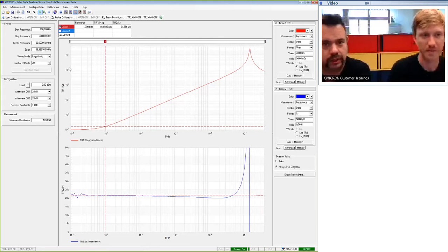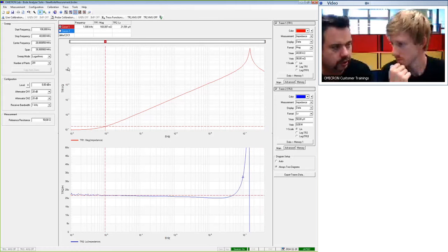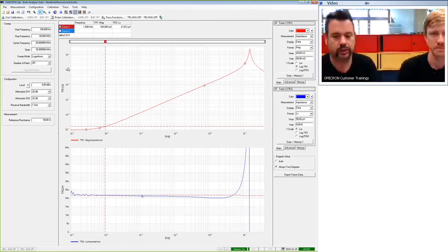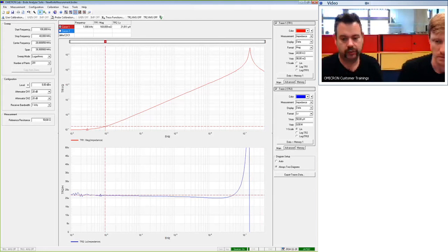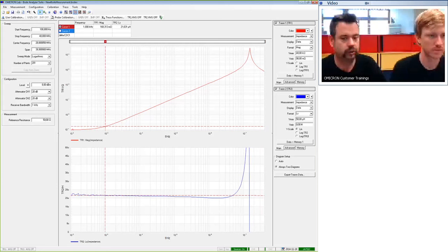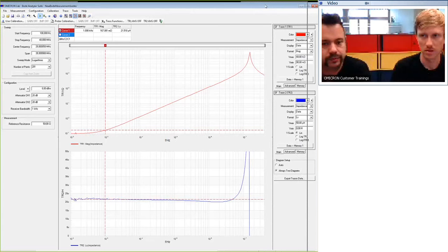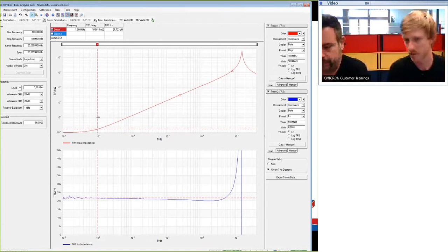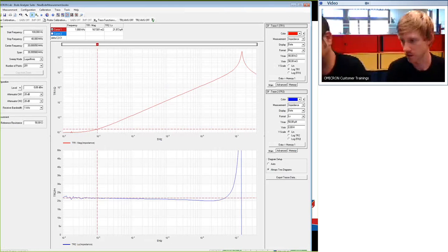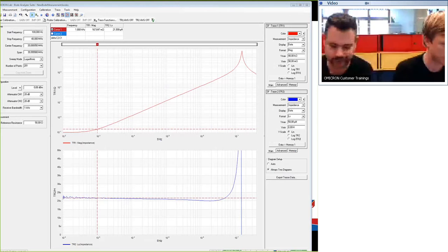What I would like to mention is that we did not calibrate the Bode 100 so far, so this is just working with the internal calibration of the Bode 100. So you can see that the calibration is switched off, and we are measuring directly with the accuracy of the device. It's just to show that, even if you don't have a cable, you have a really neatly calibrated measurement device just by booting up the Bode 100. If there are any questions, feel free to post them immediately. But I think for the moment this is nothing special. The special stuff will come later on.